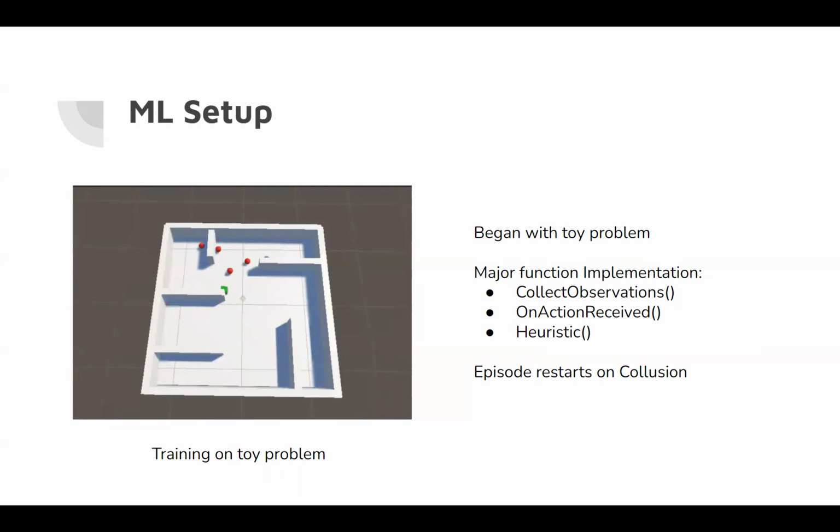During this exploratory phase is where I discovered different techniques for quantizing straying, such as changes in distance to goal, and a change in heading to the goal. I also discovered that an AI agent can be guided by a heuristic, so I experimented here and implemented two different heuristics, one purely based off the direction of the goal, and one based off the artificial potential field algorithm, and these both showed very promising results.